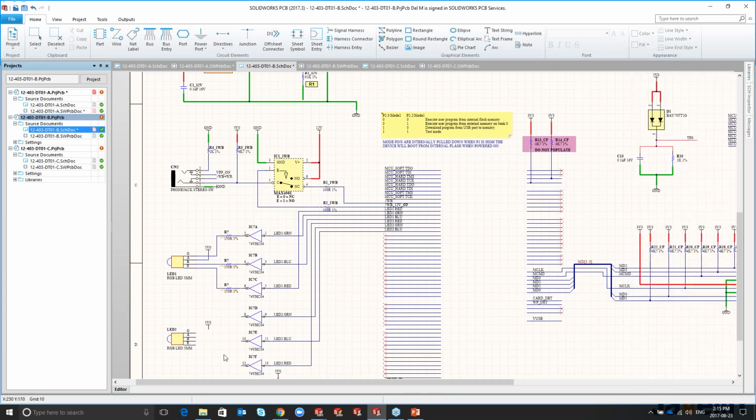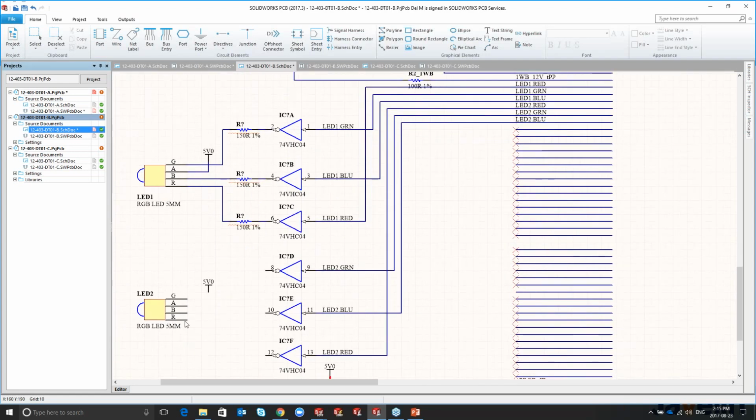Now once I've got those components placed on my schematic, I can also go ahead and complete the wiring. So we have the wire tool, and as you can see, it's fairly intuitive, the platform, and it picks off the Altium design tool that was originally the core program. So I can then go ahead and start making connections. So once I've got that one in there, we'll just simply complete these operations and make all our wire connections.